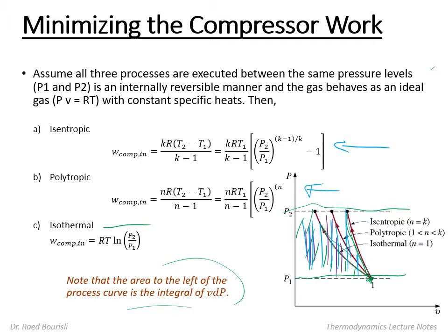These are just the integration of the boundary work term, and you'll see that this is not possible. This isothermal process, while it is the best, is not very practical. I cannot keep on cooling. I give it like 1 millijoule and I notice an expansion, an increase in V, and then I cool it. Then I compress it again, and I cool it, and I do this for 100 million times. I need 100 million stages for the compression.